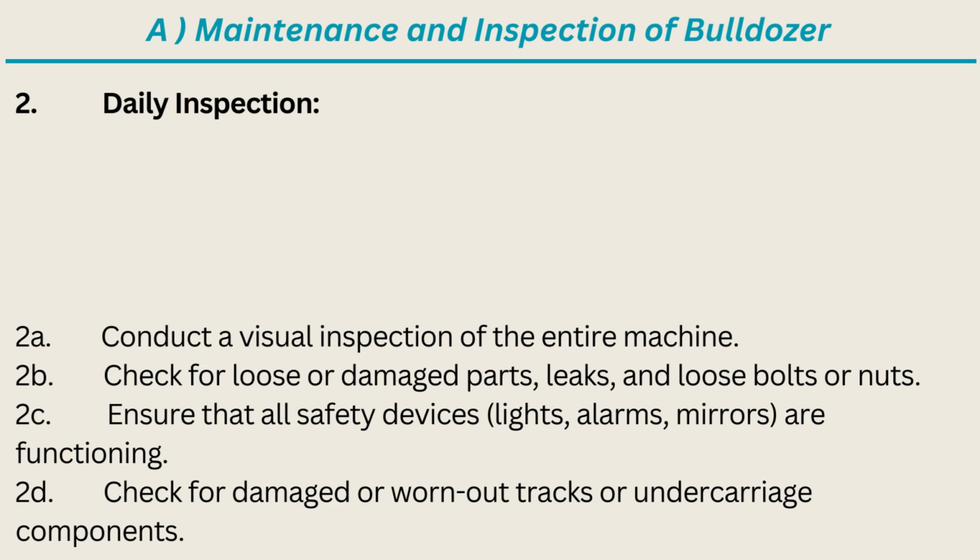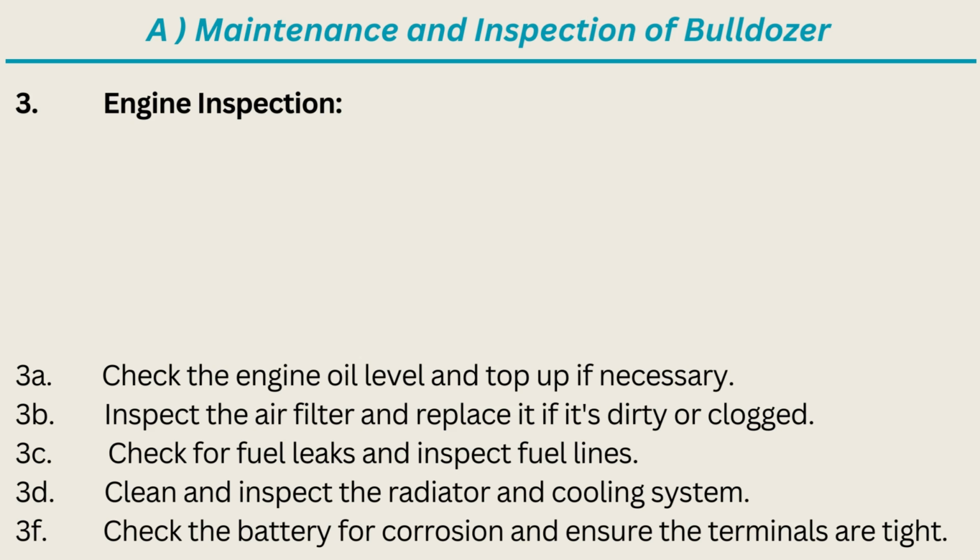2C. Ensure that all safety devices, lights, alarms, mirrors are functioning. 2D. Check for damaged or worn-out tracks or undercarriage components. 3. Engine inspection. 3A. Check the engine oil level and top up if necessary. 3B. Inspect the air filter and replace it if it's dirty or clogged.